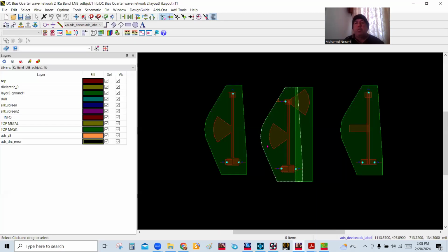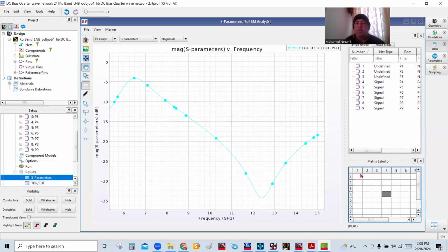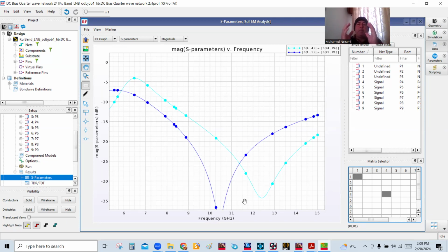And of course, what this does is it's going to resonate at two frequencies at two different places, and therefore it will broaden the bandwidth of this bias network. And I can already see that, because when you go 1, 1, they didn't resonate at the same place. But if you altered the length, if you tuned it so that they're right on each other, you can see that really this one has a much wider response, okay?